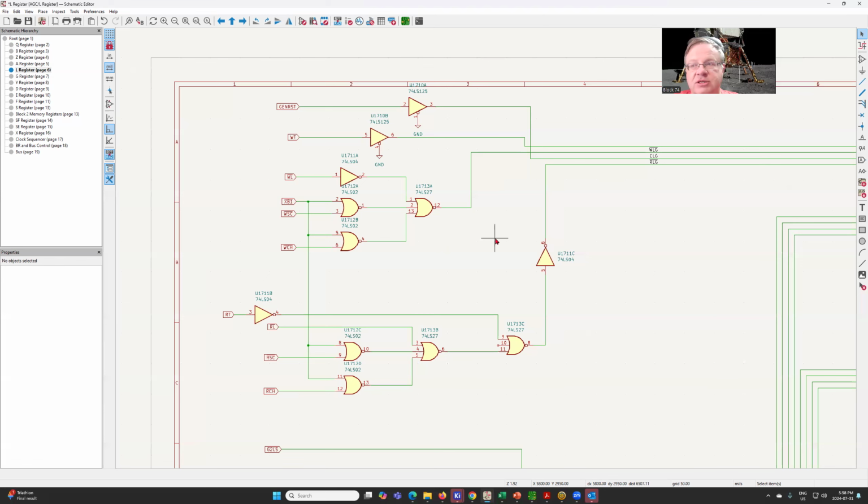Now, as you look at the sequence of control pulses that make up that instruction, the computer actually does the appropriate logical operations and inversions to generate either that AND or exclusive OR, only using OR on the actual write lines.